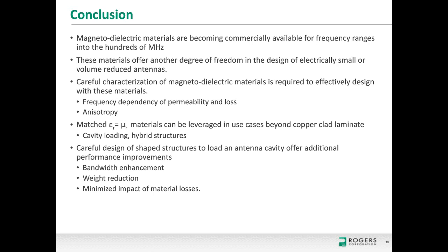And so it'll be dominated by basically a series mixing rule between the dielectric constant of the second material and the dielectric constant of the magneto-dielectric material. Let's say I've got a permittivity of 5 in the z direction, and I take a material that has a dielectric constant of 2. My rough volume fraction is 10% dielectric constant of 2 and 90% dielectric constant of 5. I'll get a dielectric constant that's somewhere around 3. And you can almost go back to your Physics 1 textbook, where you look at that capacitor example where you do a capacitor with air in series with a high dielectric constant material, and use those equations to calculate out the effective permittivity in that case.